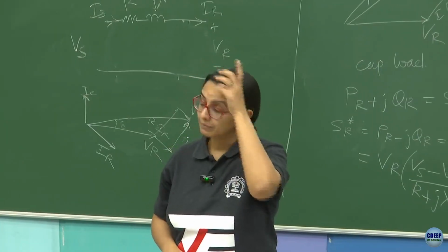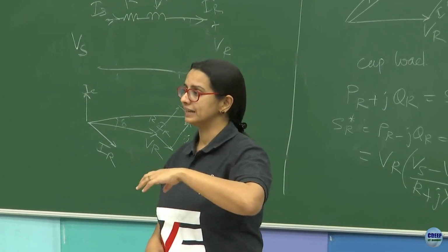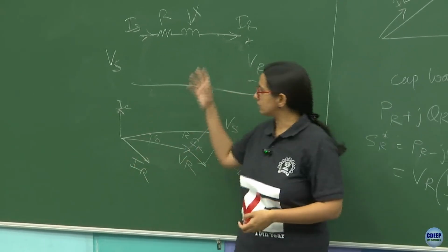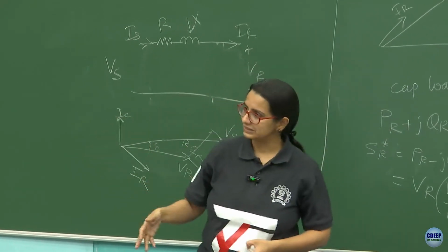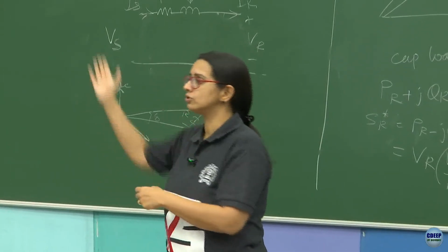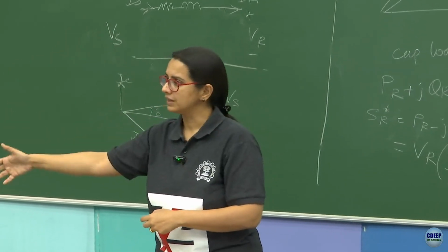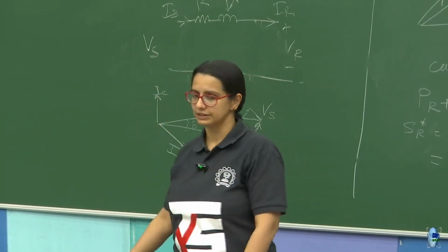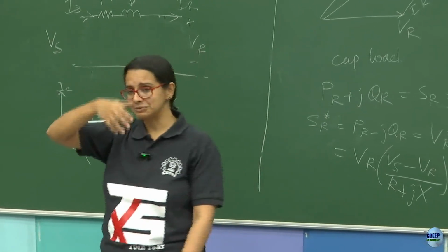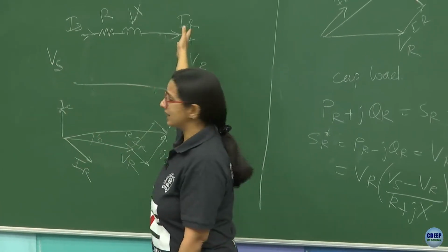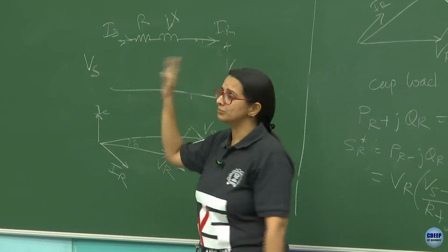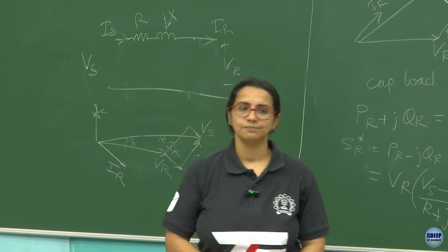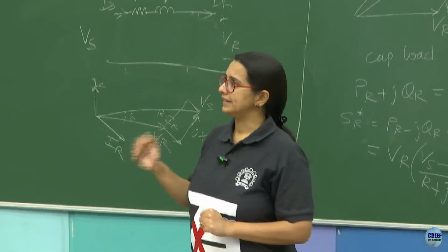The NL there means no load, FL there means full load. And so the term is simply, basically, when we talk of voltage regulation in power engineering, we are really talking of, as you move from no load to full load, you're going to see a voltage drop, and that's how you measure the amount of voltage deviation and hence voltage regulation required. Okay, so in this particular setup, if you were to draw no current, then your Vs and Vr are going to be exactly the same, which is why Vs is in fact said as Vr no load. Make sense? Any other questions?